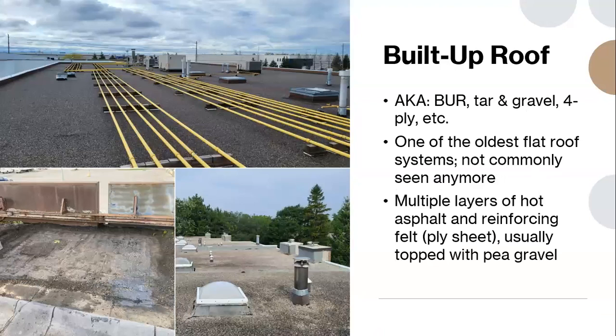Okay, so next up, when it comes to flat roofing, one of the oldest and for a long time the most popular roof system would be a built-up roof. Some other names that you might see would be just the shortened form: BUR, tar and gravel, 4-ply. Typically, if you're hearing these terms, they're talking about a built-up roof. So again, for over 100 years this was the primary flat roofing system. It was a very great durable system with a lot of redundancy.